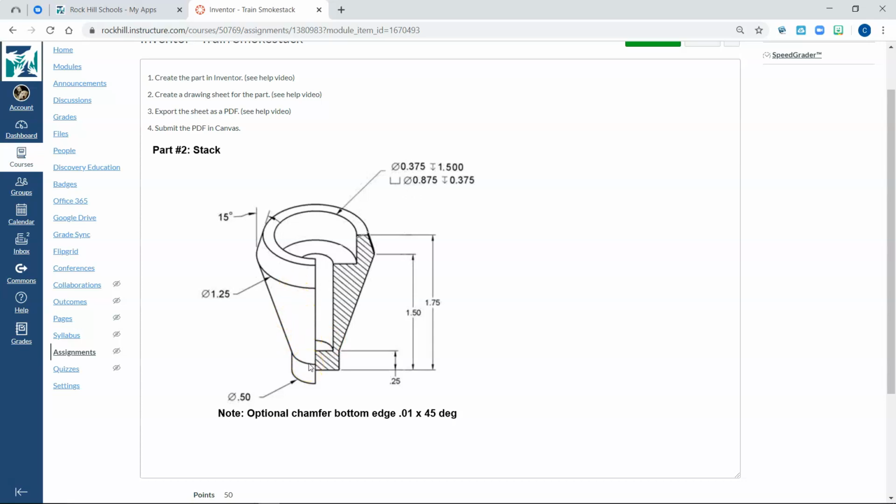So imagine taking a dime and a quarter and holding them an inch apart, and then creating a shape in between those two. It starts off small and then gradually gets larger. We also have to make sure that the circles are lined up concentric, meaning they have exactly the same center point. Otherwise, our quote-unquote cone shape would not be symmetric. It would be off-center. So we're going to make sure that the bottom circle that we just drew and this larger circle have the same center point, and we're going to make sure they are 1.25 inches apart.